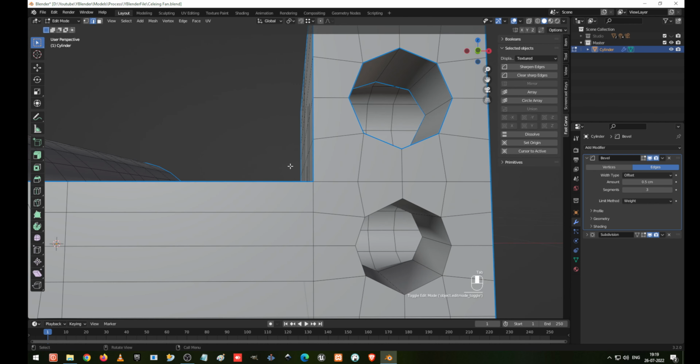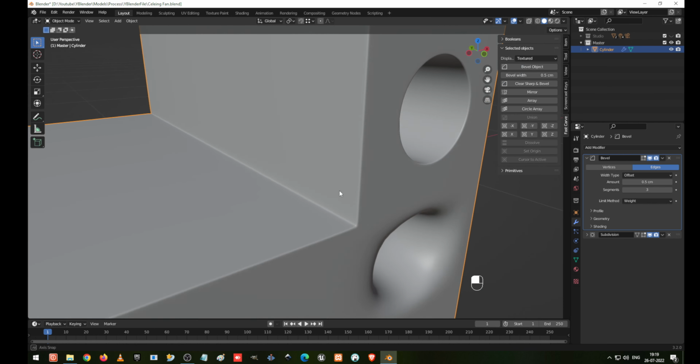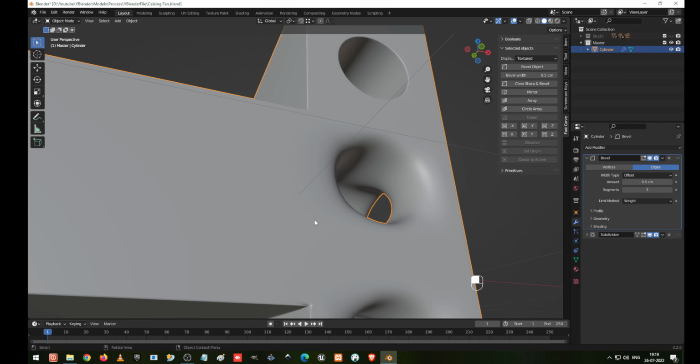So I press Control. Before that I select these two, and now I hope what is our requirement has been selected. Control B to bevel. Some locations we require manually, so I just give the small edges. Okay, and here some issues, so we have to disable this, clear edges, and select this one and make sure. So now it looks better.